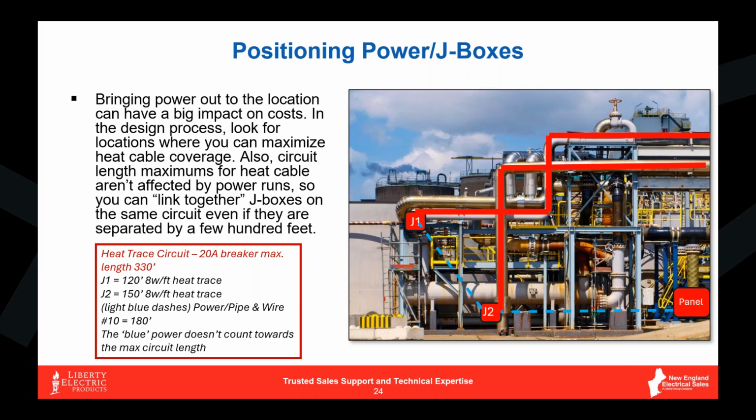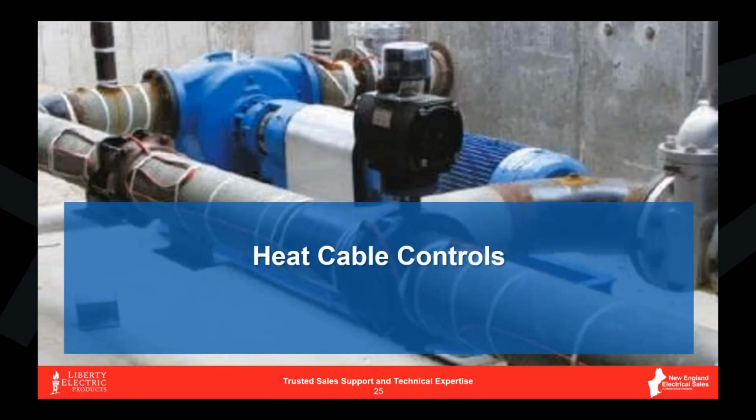So the easiest way to remember it is, if it's heat cable, it counts towards the circuit length. If it's not heat cable, it doesn't count towards the circuit length, okay?